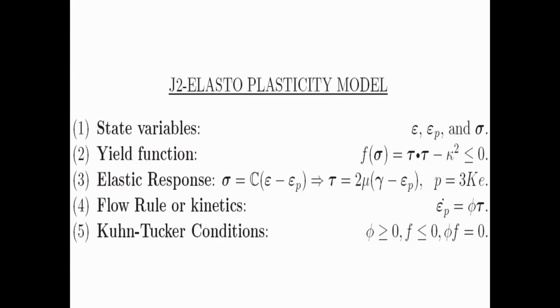So till then there will be some deformation, I mean volume change will be there, but after that it will start flowing and there will be no volume change, right? That's correct. That is why if you look at this, E times 3K is equal to pressure is written. You don't have any plastic strain coming into picture in this. You can see that?